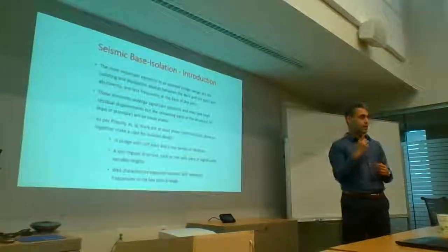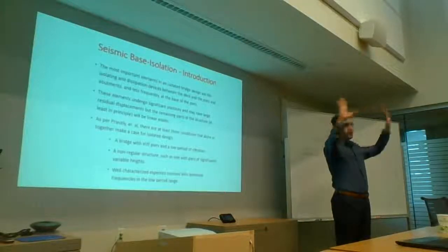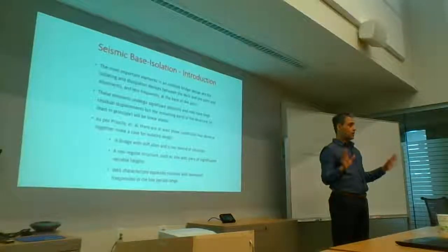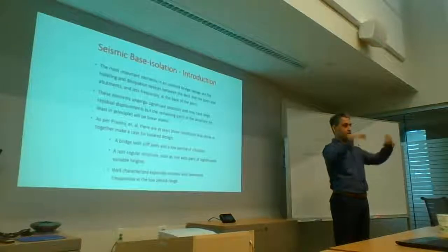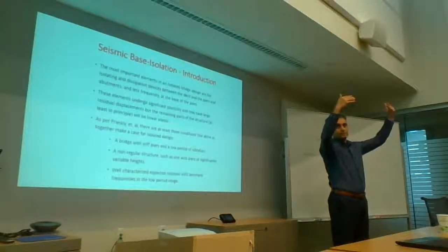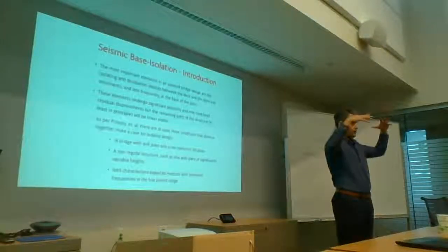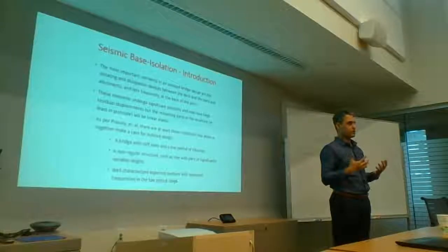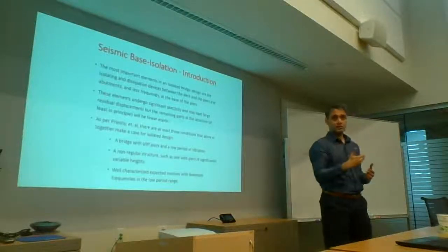A different scenario arises when you look at a lot of the older bridges with massive wall piers in rivers or otherwise, because now you've got almost the same mass in the substructure as you do in the superstructure. So there, if you isolate, you've only isolated part of the problem. And now if your wall pier is not very ductile, it's stiff as hell, it's really strong, but the earthquake is going to push it to its limit, it might just fall.